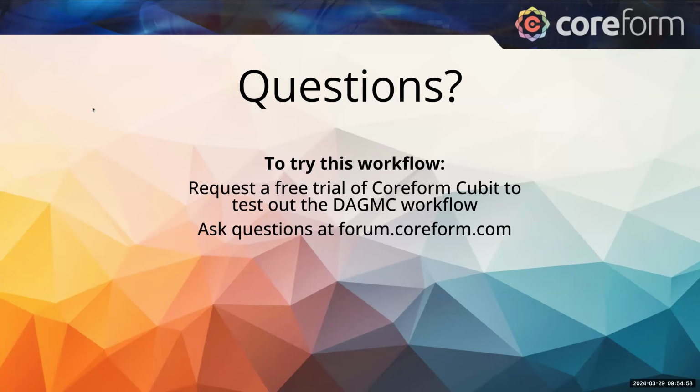Yeah, so I didn't have time to go into more detail on that, but I will try to touch on that again here. In the past, we used triangles that were generated from the faceting engine for graphics within Cubit, which is different from the meshing engine itself within Cubit. The faceting engine was really just based on what was giving you the visualization of the model, which isn't meant to be representative of the underlying analytic representation.